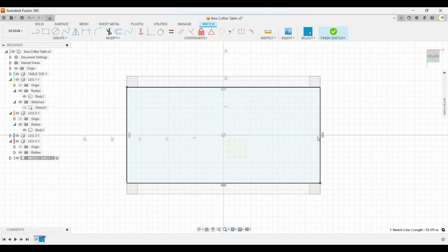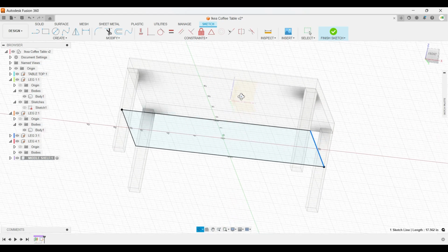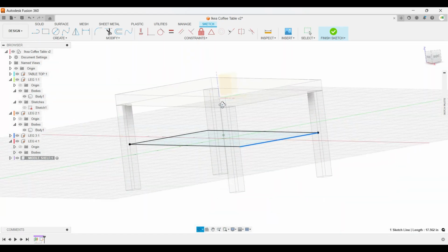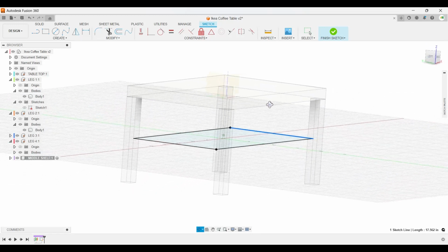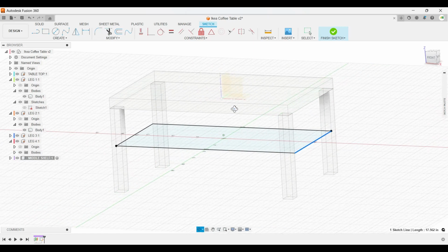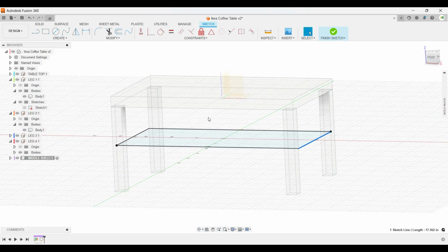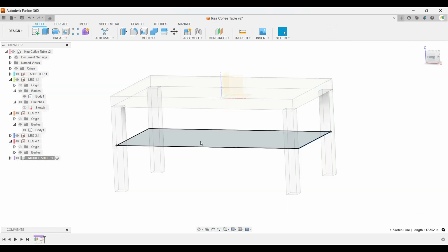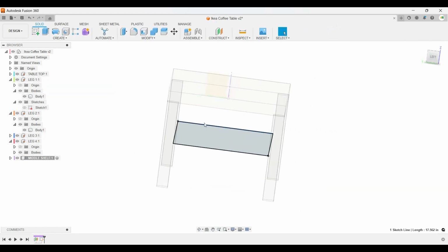It's all black and I can't drag it at all. So if you rotate it, you could see that we have created the middle shelf geometry that we're going to need. I'm really saying geometry, but really it's just the profile. The geometry comes in after we add the volume. So here we're going to click finish sketch now that we're done with that. And then the thickness of the shelf is 1/2 inch. So we're going to click extrude.